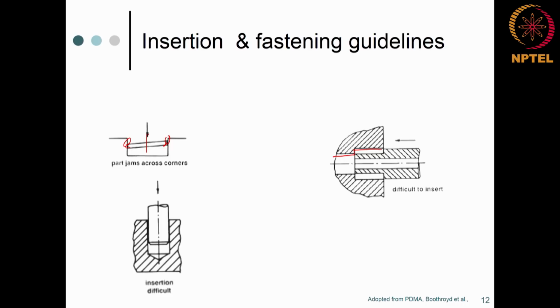What is the problem? The hole diameter should be more than the inserting part. You want a fastening kind of thing, no? So fit-wise, it's still the snug fit, like a press fit, 0.1 mm, 0.2 mm. Fine. But the deal is this.